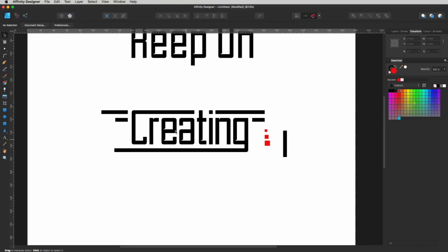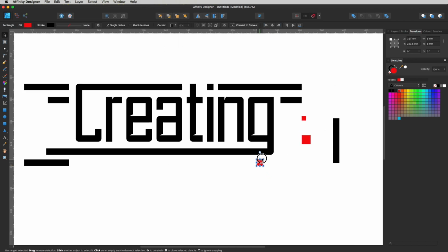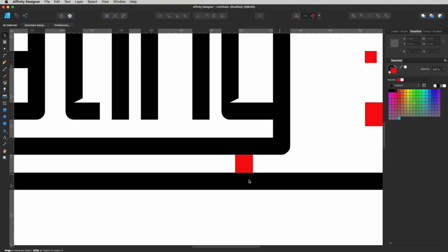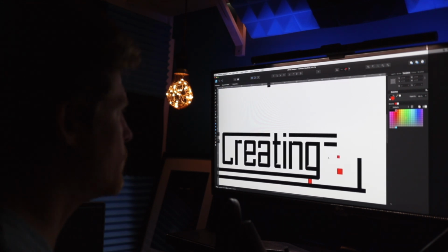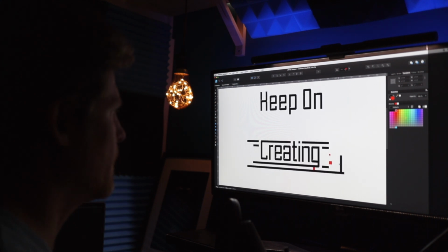Now what I need to do is basically select this top piece over here. I'm going to alt drag this all the way down to the bottom. Okay, and this is going to be the 6x6 again too. So grab my little 6, I'm going to click and drag that all the way out. Just make sure it snaps there. Okay, yeah, that's all there. Cool. And we're going to need another one extending past the edge of this G here too. So just select this one over here, click and drag, bring it all the way down, make sure it snaps. And we've got the, yeah, that's cool. Okay, just drag those right off the page over there.